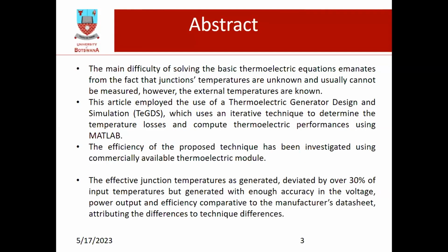In summary of what we have achieved, we found that the main difficulty with thermoelectric generators was that solving them using thermoelectric equations emanated from the fact that operation was based on external temperatures, while the junction temperatures, which are the effective temperatures that produce the power output or the performance, were not known.